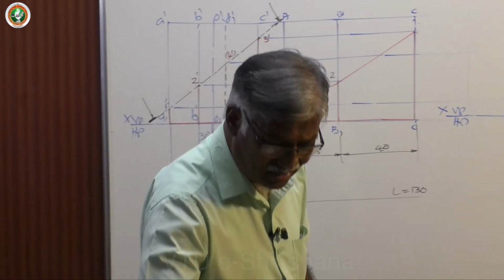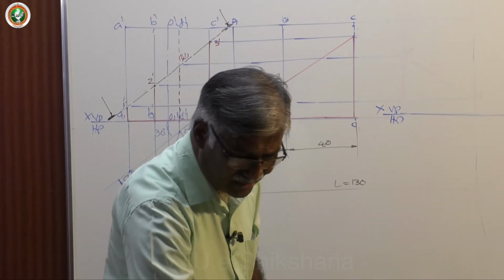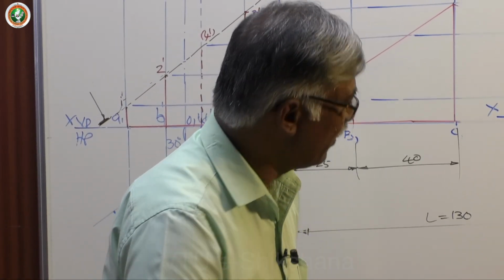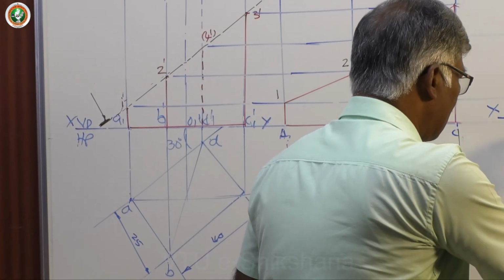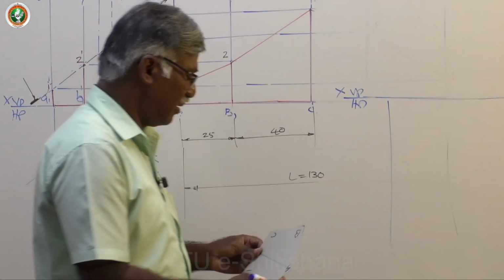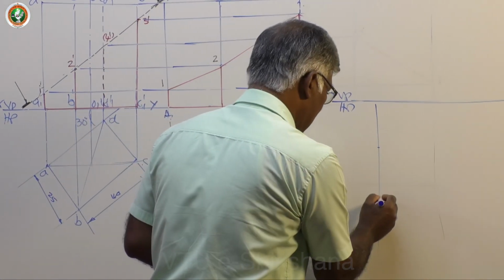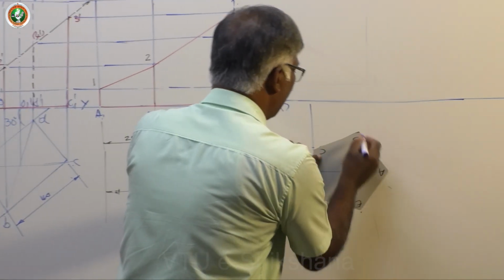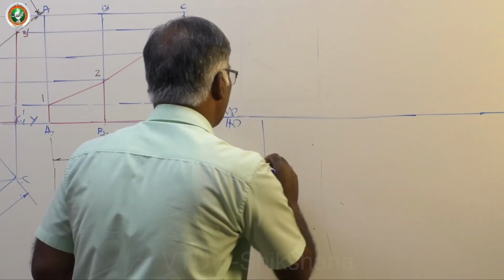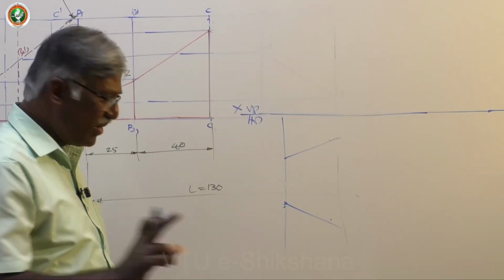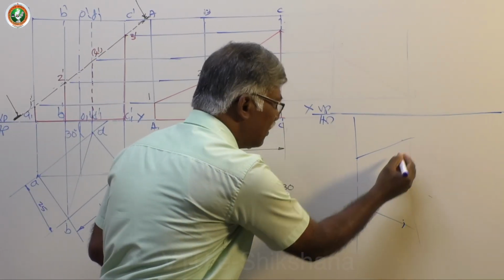So here is the very important information. Whenever you have pentagon, you must be very careful. Take the perpendicular line. On that you mark the side of the pentagon and then keep 108 degrees line, and then take same radius and draw arcs.